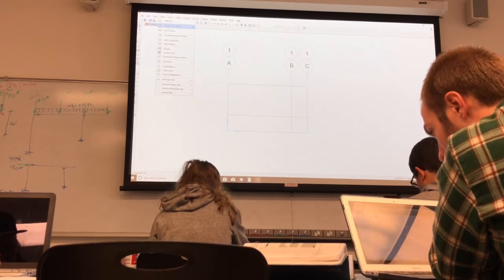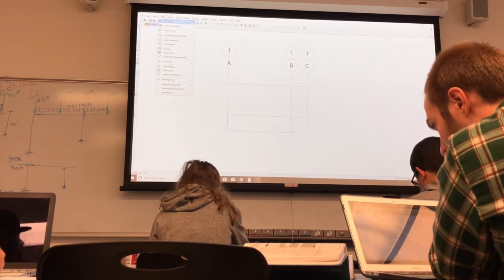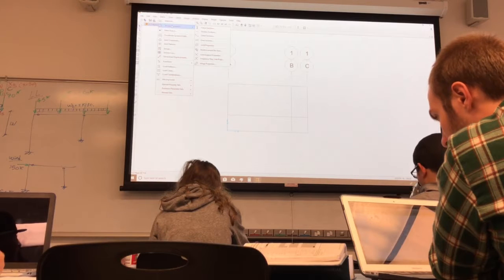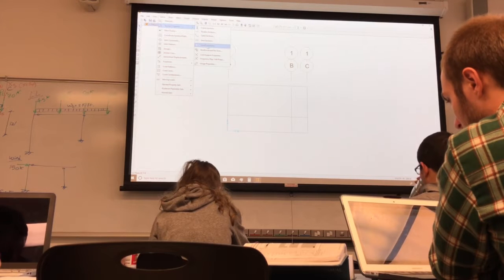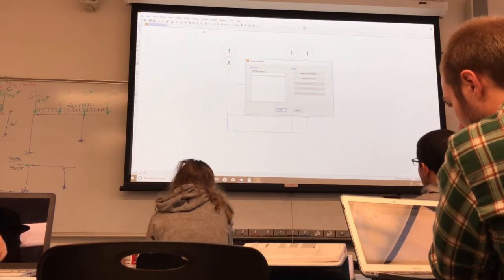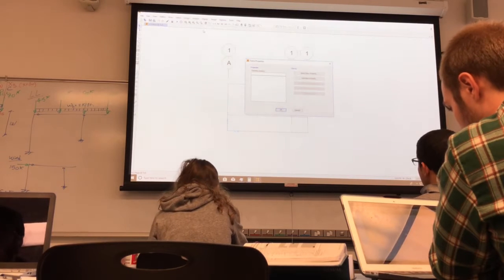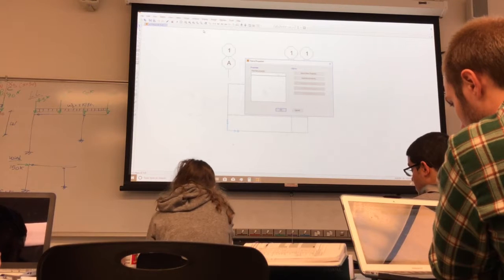So I define the material, and now I need to define a section property. As I said, we go from up to down. Section properties, we have frame sections. We don't have any tendons, cables, shell elements or solid elements. So only frame sections, so specify frame sections. And now we need to specify a W14 by 109, W21 by 44, W14 by 99.